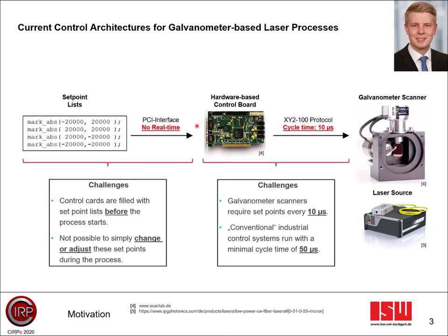Due to the PCI Express interface and the mentioned list format, the set points cannot easily be changed in real time during execution. Furthermore, the commercial control boards offer no possibilities to integrate customer-specific logic or to adjust the algorithms running on the controller. Consequently, no closed loop or advanced control strategies can be realized. However, the control boards can also not be easily replaced by conventional controls or real-time operating systems because they cannot fulfill the required cycle time of 10 microseconds.